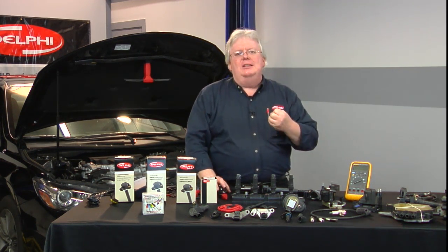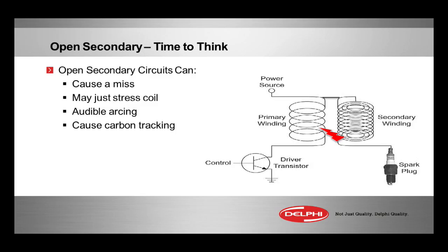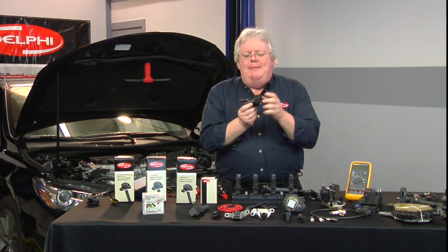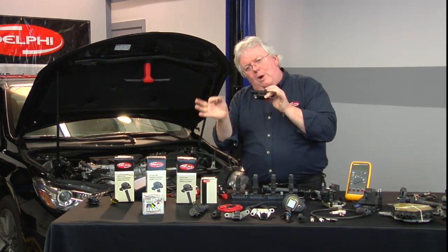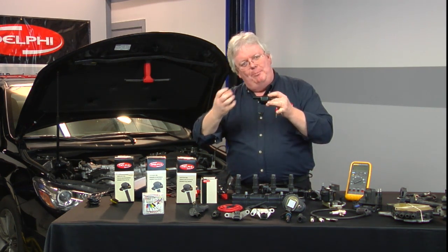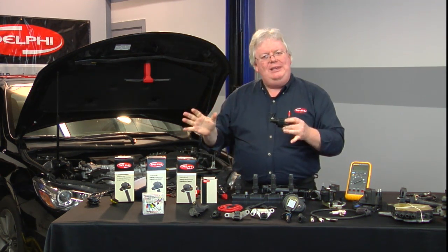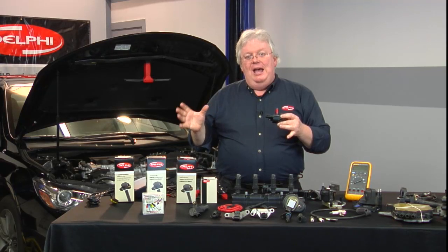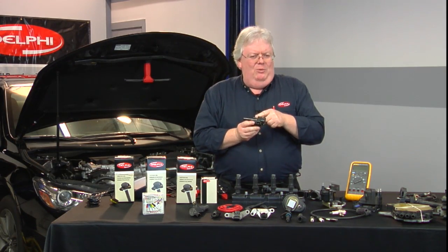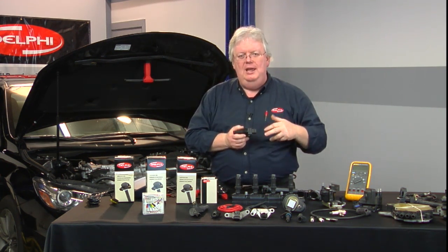Make a little trace like a scar internally between the primary and the secondary, zap like that, and that's when we have a permanent trace that even when the secondary high resistance issue is repaired, example being this GM coil near plug, where I have a short little plug wire going down to the spark plug, if that's got high resistance because of the internal circuitry of the plug itself, or because of maybe the connection at the plug wire terminal onto the spark plug, whatever the case may be, any high resistance secondary, higher than normal, can cause the spark to say, you know what, why don't we just jump across from the secondary to the primary? That's a good path back to where I started, and it makes that trace.